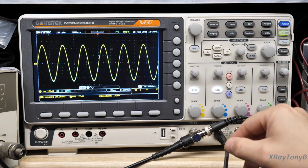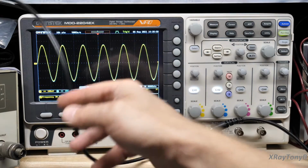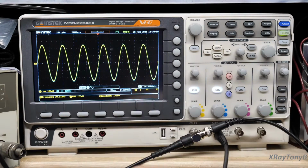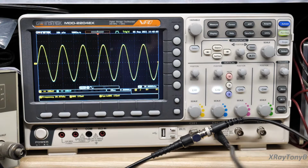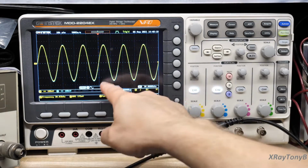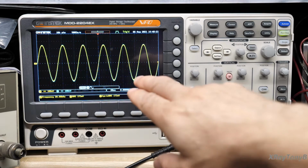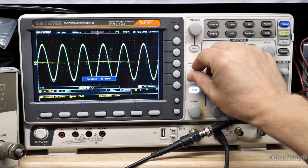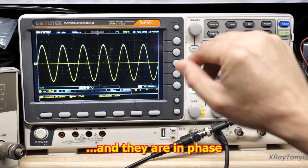there's your oscilloscope, okay? And right now, I have the signal generator coming out of the back of the MDO going into channel 1. And then I have it going through a T and connecting it also onto channel 2. So channel 1 and channel 2 are both connected to the signal generator, and therefore, if you notice, both of them are falling on top of one another, both of the signals. So channel 1 and channel 2 are perfectly aligned, right? And that's what it should be. Okay?